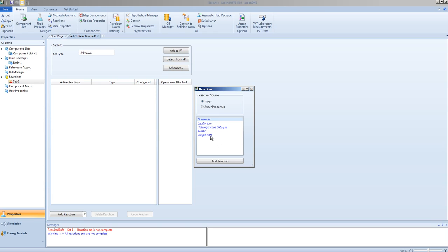For the kinetic reactors, you specify kinetic models for the reaction, and HYSYS then calculates the rate of reaction. This rate is done on a per unit volume or unit mass of catalyst, or based on the residence time in the reactor vessel. Note, kinetic reactors may not always reach equilibrium, as there may not be sufficient time for the reactions to take place to the point of equilibrium.